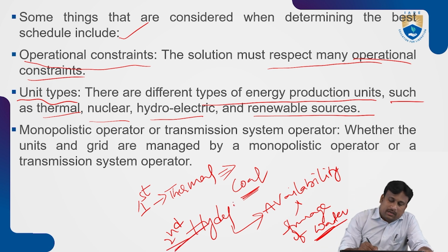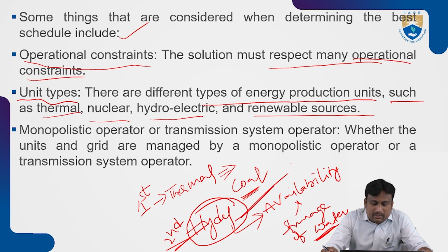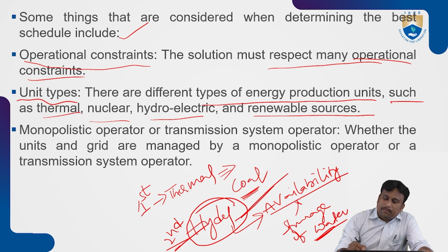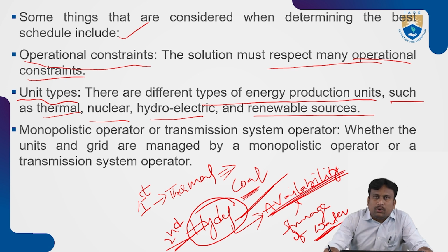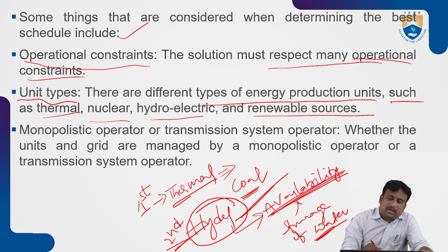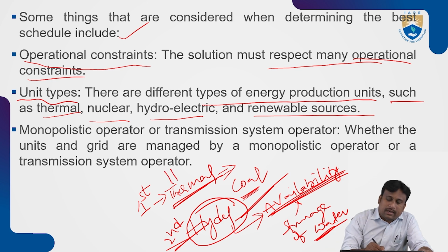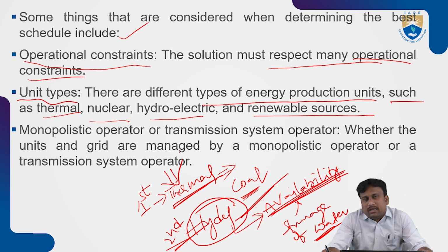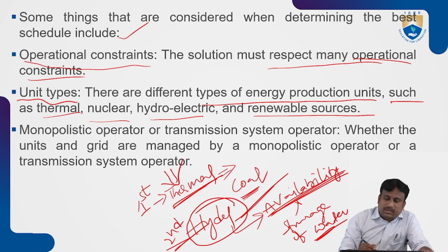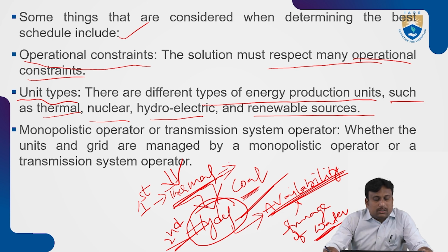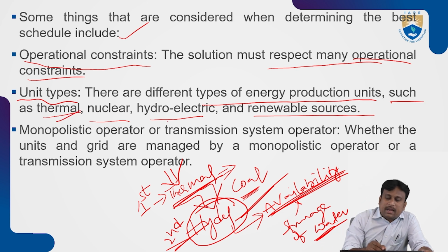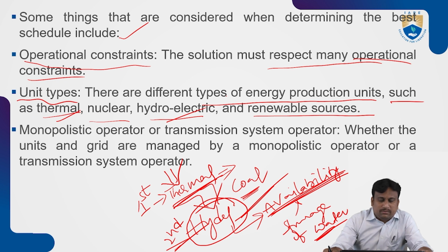Even though the running cost, whatever it may be, the investment for this is minimal compared to thermal. But if you compare the availability, the source availability is continuous in thermal. So most of the plants and most of the loads are interconnected to thermal power plants. Meanwhile, they are interchanging their exposures to hydel. So thermal and hydel will play a key role in the power system network.